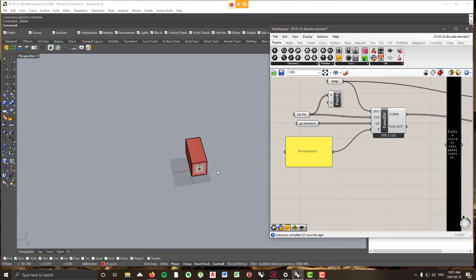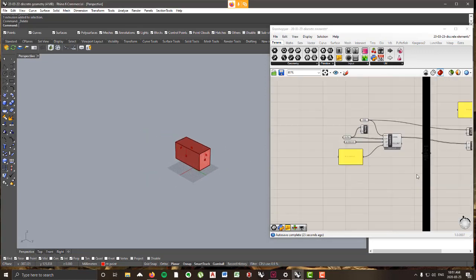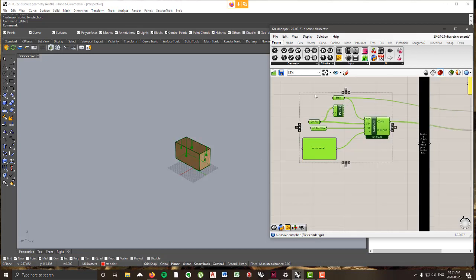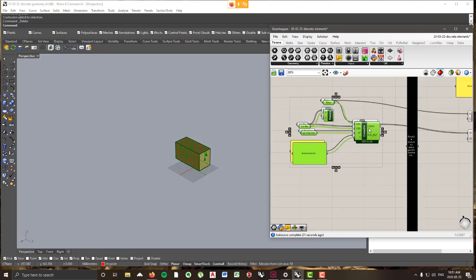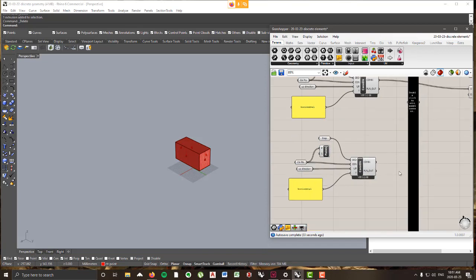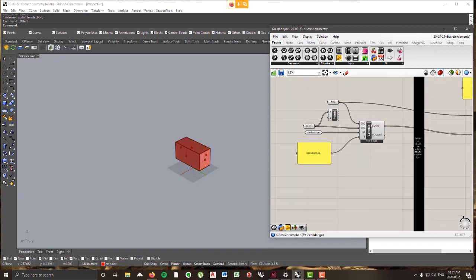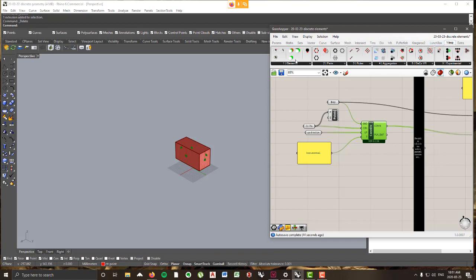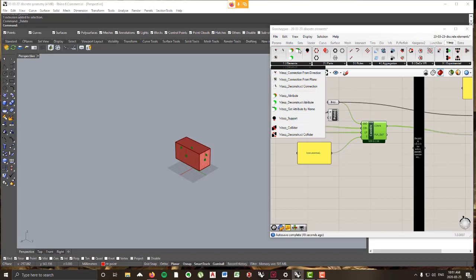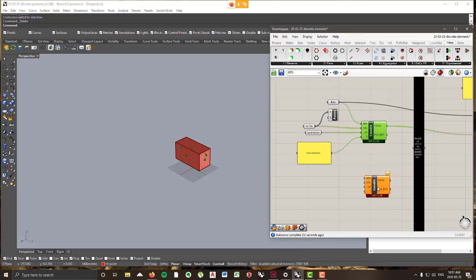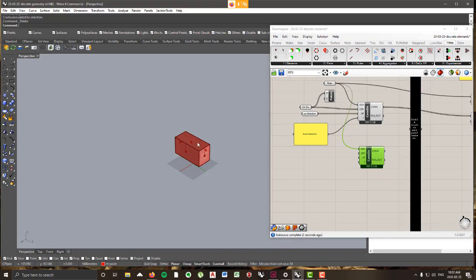We can now start to make a vertical connection. What we can do is copy, Control C, Control V, all of this connection stuff. You know what I might do actually? I might just remake this as kind of a review. So why don't we review that? I just deleted that. I'm going to go to WASP, Elements, Connection from Direction. So same component we have here. The geometry is still going to be the brep, same brep here. But I'm going to set new points.